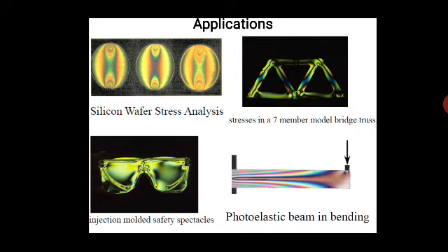So here also we are going for a material called a transparent material, or a silicon or rubber material. So it is very easy, and applicable for your truss problems. Along with this, photoelasticity can be applied for analysis of safety spectacles in industries, and we can prevent the failure, or we can justify where the material is taking the load whenever the spectacles are opened and closed.